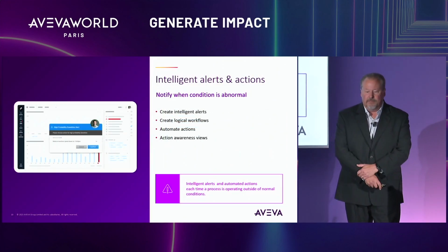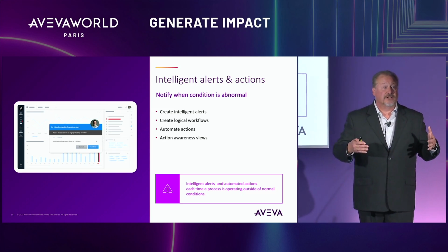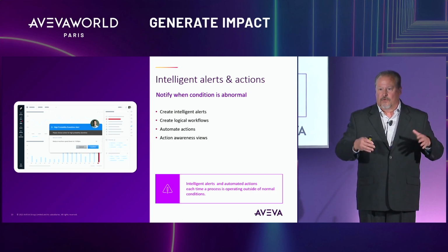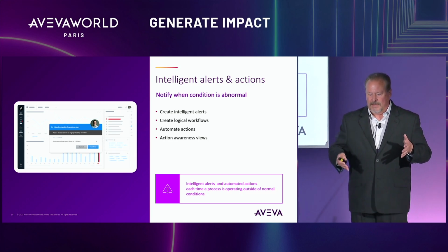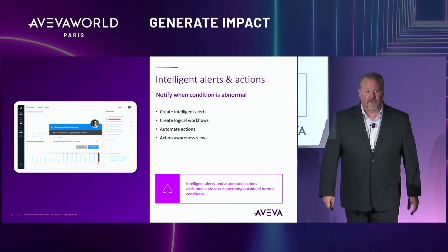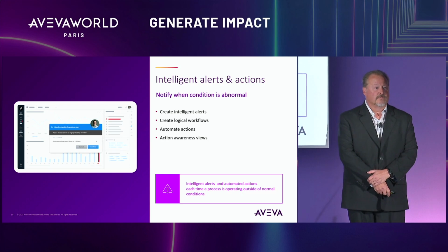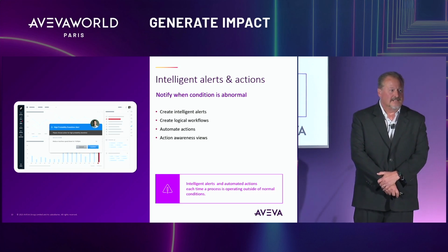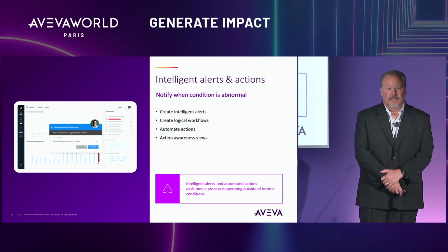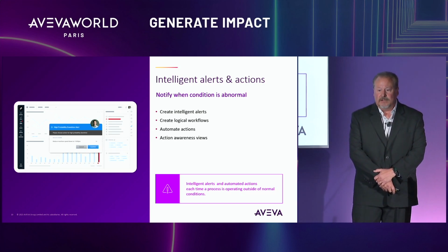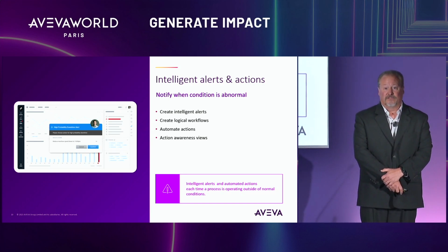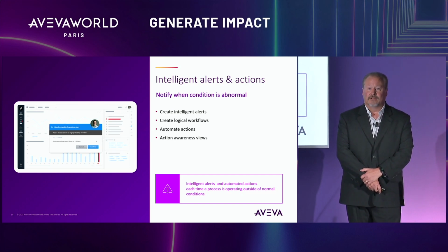The other piece is, once you put a model into operation or runtime mode, it'll constantly score your real-time data, new data, against the model. You can either configure, or there are some automatically configured, alerts and actions that can be driven to you via email or text. You can get those alerts and take action before you have a problem. That may be adjusting some parameters down on the plant floor. It may be reacting to a pending failure condition that you can fix before it becomes a failure.